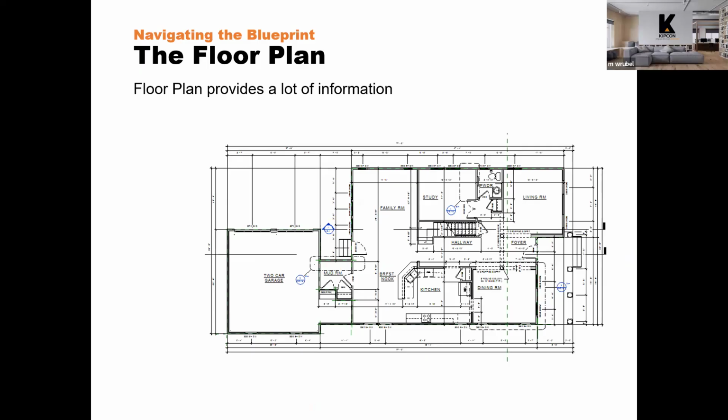In the case of architectural plans, it'll show you the different rooms, obviously. There are internal and external dimensions. That's what you see, these dimension lines all over, showing the dimensions in feet and inches to the outside of the building. One of the things that is not shown in this particular presentation, and I want to touch on, is the drawing scale. When you look at a plan view sheet or any design plan sheet in the set, there's going to be a scale.